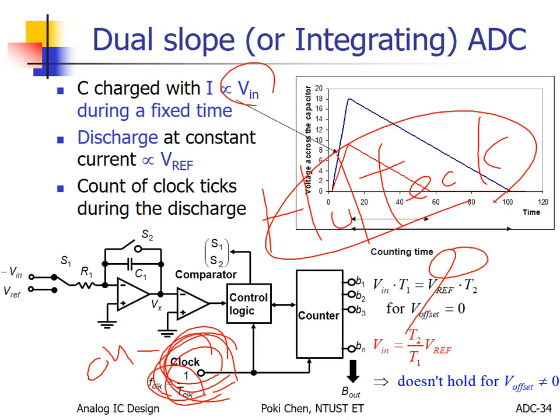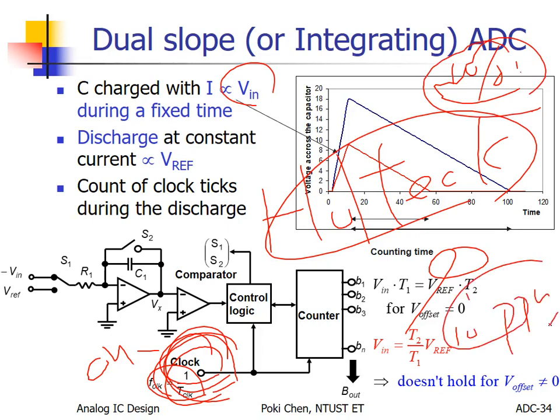According to process variation, the deviation of output frequency is still tens of percent. But after calibration, to my memory, they can make it around 1%. And the drift may be tens of ppm according to temperature variation. I think that is good enough for daily life applications.